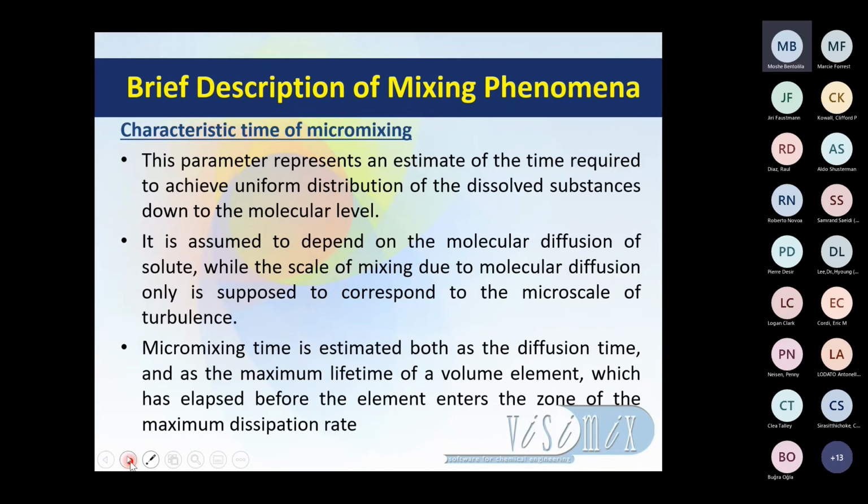If we have an average diffusivity, but around the impeller it is 1,000 times more, and my process is a fast process, maybe we need to have a drop or semi-batch and drop into the place that is very highly dispersed, with fast velocity, and we are controlling our process. So you can understand that we are talking about the integration between different levels, because mixing is a multidimensional phenomenon that we need to take care of.